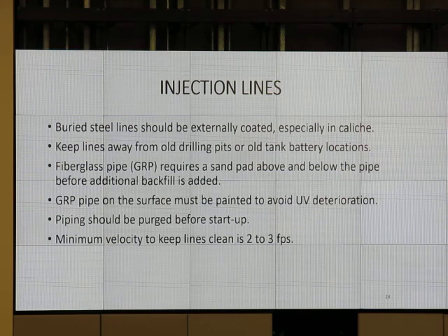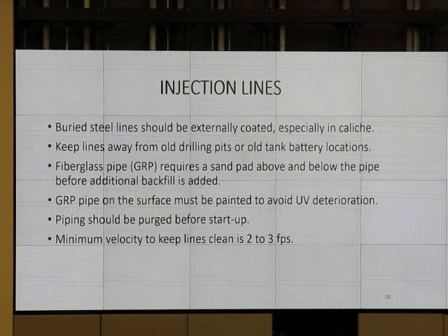We need to keep lines away from old drilling pits or where old tank battery locations have been. When you're doing your water flood design, remember you're going to be putting in individual tank batteries. There's going to be pads that later you're going to put in, and you're going to be running lines. When you run those lines, you don't want to go through these old tank battery locations. There's lots of things spilled, and the soil can be contaminated, causing external corrosion.